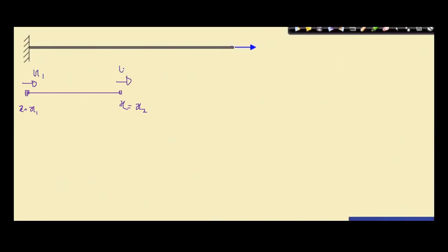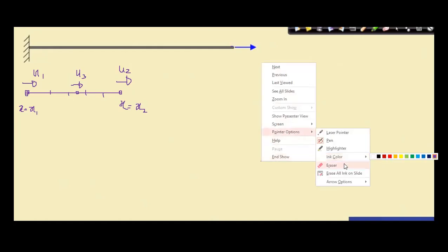So we need the displacement in terms of, we know the displacement at the ends, it's u1 and u2. Okay, so we only know 2 points. We need to know what the displacement will be at any point. In order to do that, we need some expression, but you only have 2 points, so you can only write a linear equation. If you have 3 nodes, you can write a quadratic equation like ax squared plus bx plus c, right? For this case, you can't have that. You only have these 2 equations.